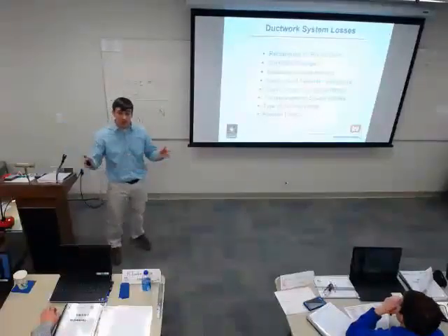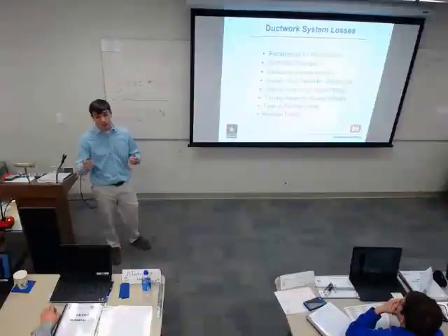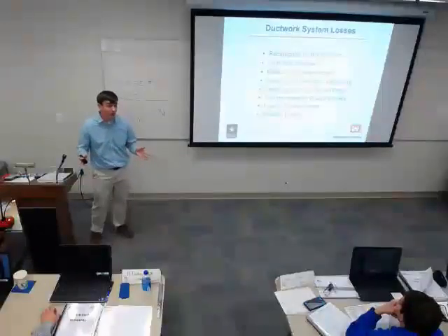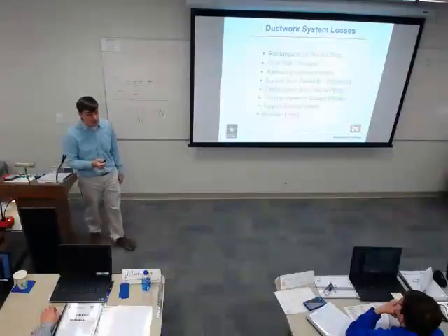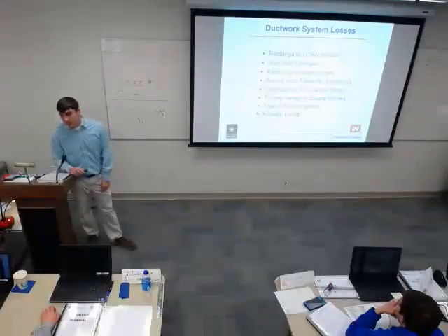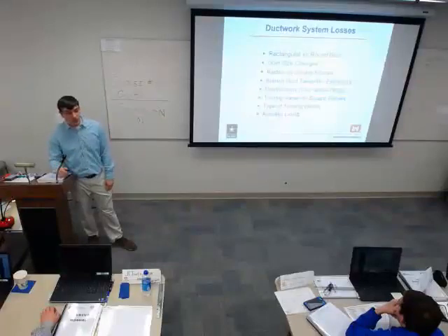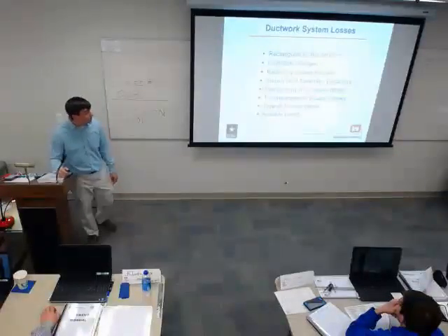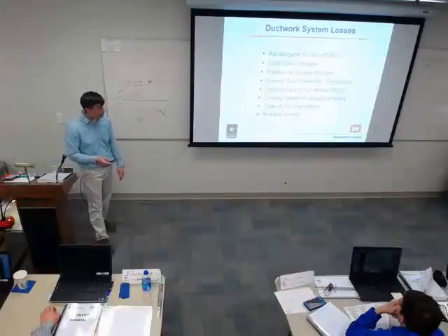Do I look at every single duct size through the drawings? No, but I do look. Apparently that designer didn't, because every single duct size had been changed by the contractor. His rationale being, I want to keep the velocity the same. No, that's the engineer's decision. He picked your velocities and how that duct was sized. The contractor just wanted to put smaller ducts in.